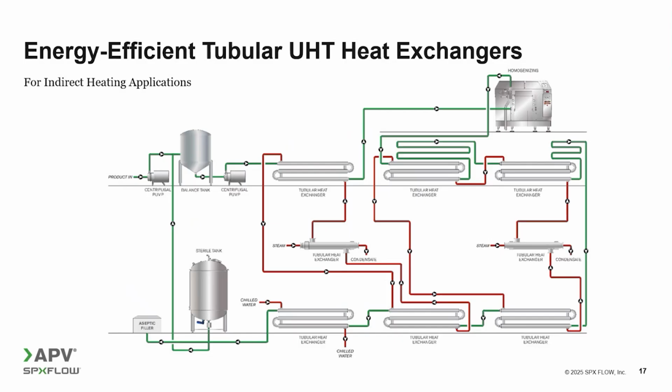For example, one loop could be dedicated exclusively to heating. So we could be running at higher temperatures, and in that way, we would try to optimize as much as possible the sterilization section. The other loop could be focused, for example, on the cooling or trying to maximize the regeneration efficiency with lower temperature set points.